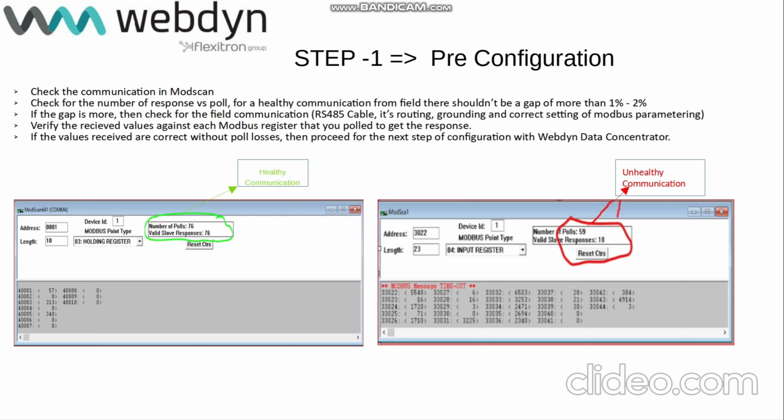Generally, the holding registers start with 40,001 as a sequence in the registers. Sometimes you can simply mention it as 01001 or something, or even 40,001. Both are similar if you are querying the holding registers. Based on that, just click on the connection and see what you are getting as a response.